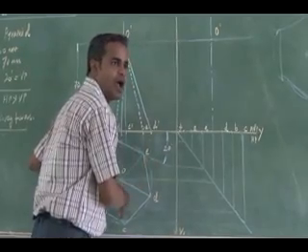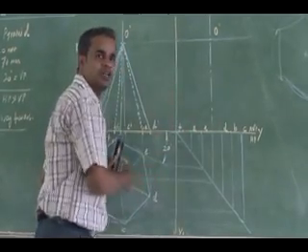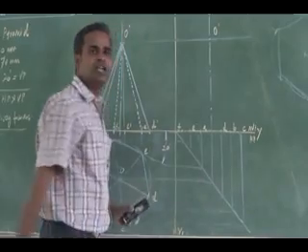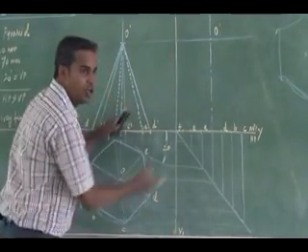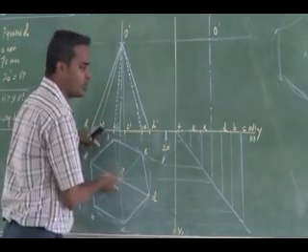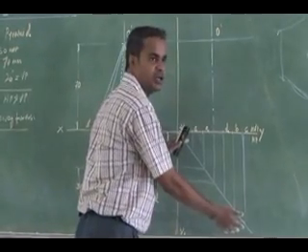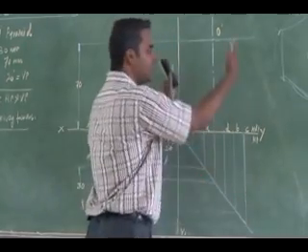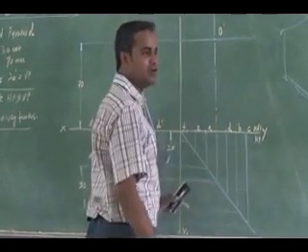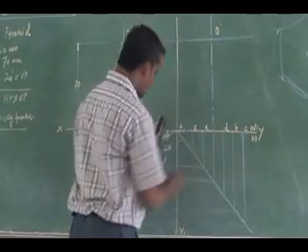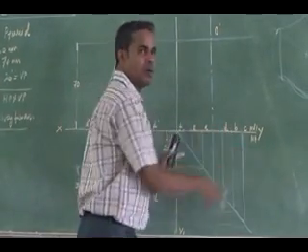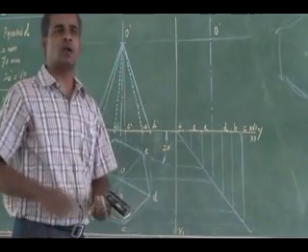The top view points and the front view locations are linked with a 45-degree line. Okay, so I have drawn a 45-degree line. All the base points, including the apex location, I have projected to the 45-degree line. Then I have projected to the left side view. So I have marked the apex. Then the corresponding base corners we have to mark. They will fall on different locations.